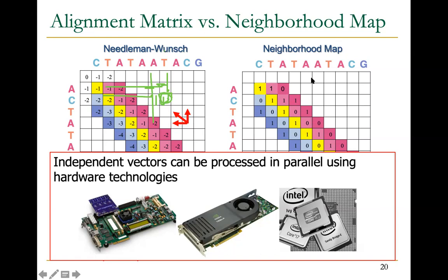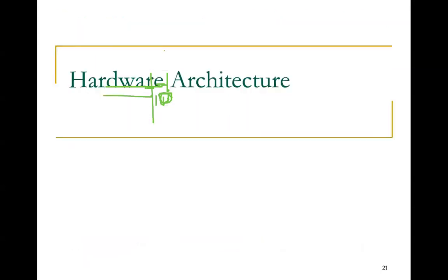However, in the GateKeeper, every cell, or the module to calculate a single cell or multiple cells, can be replicated to parallelize inside the problem of solving two sequences. So you can have parallelism at the level of sequences as well as at the level of the entries of the DP matrix. And this is where we got the 130x speedup, for example.